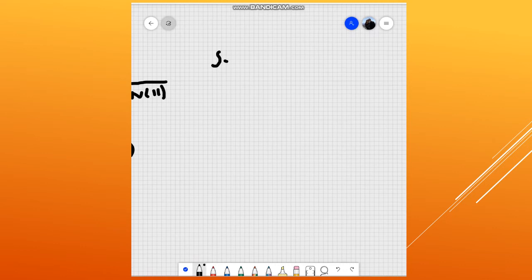As in the previous question, we will do the same thing and find again the maximum potential retention S, which is equal to 1000 over the curve number, in this case 92.3, minus 10. We will find here S is going to be 0.83 inch of depth.